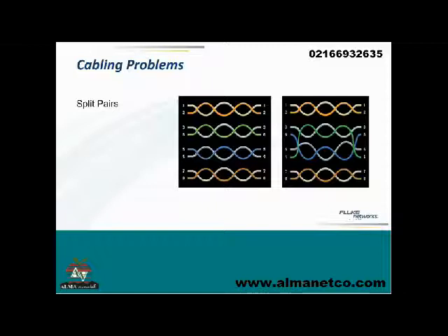You really don't want this, and that's why it's important to make sure, if you ever buy a cable tester, that it can tell split pairs. The really inexpensive ones that just use DC testing can't tell the difference between the cable in the middle and the cable on the right, but your network equipment certainly will.